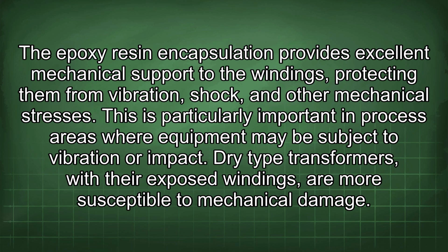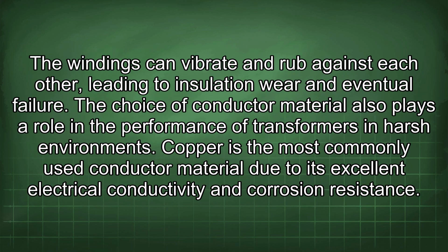Dry-type transformers, with their exposed windings, are more susceptible to mechanical damage. The windings can vibrate and rub against each other, leading to insulation wear and eventual failure.